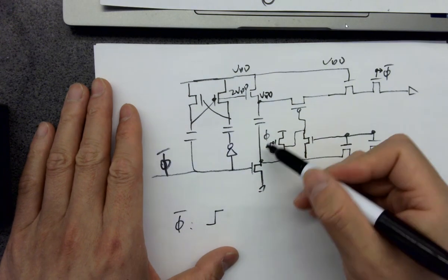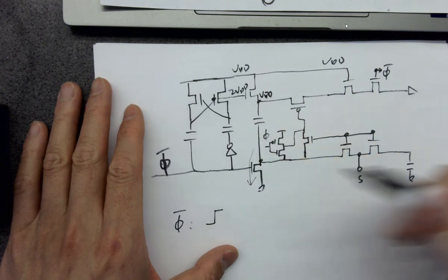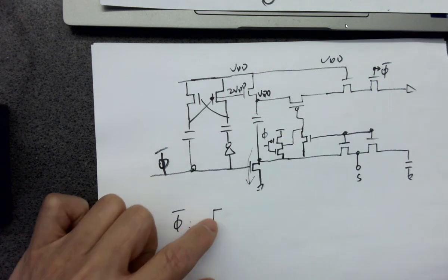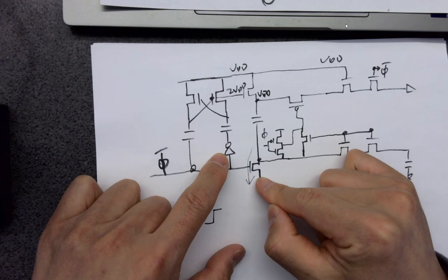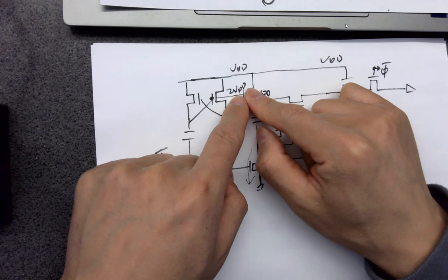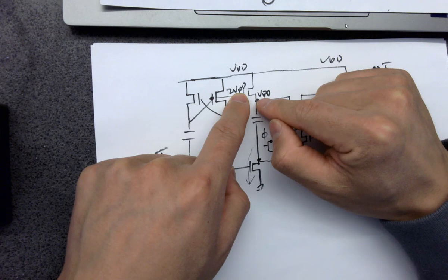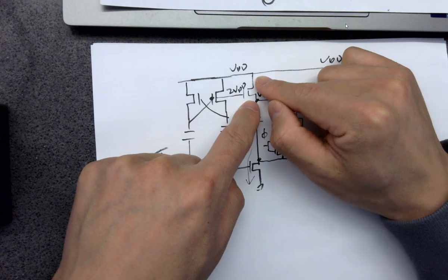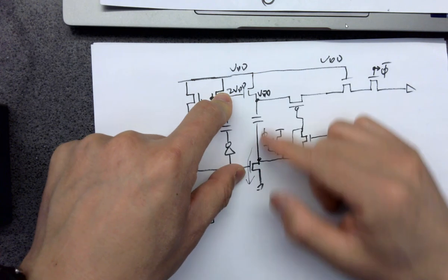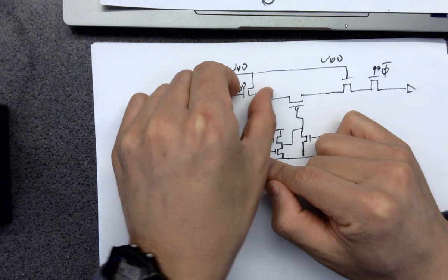And because it's a rising edge, this is pulling as well. This NMOS is pulling to ground whenever this voltage here is a rising edge. And it's pushing, and you're getting 2 VDD, which is perfect. This 2 VDD is going to keep this NMOS wide open, so you have VDD available at this source, for this pin. So this is able to see this VDD and start pulling charges from the VDD. And also, because this is shorted to ground, the charges have a place to go. So whenever this is pulling and this is wide open, it's all on.